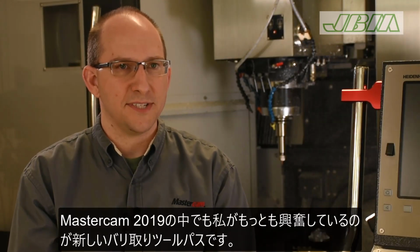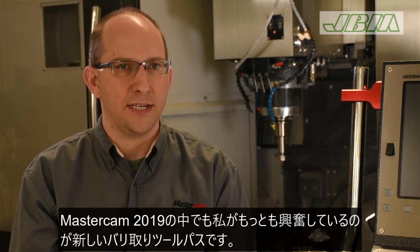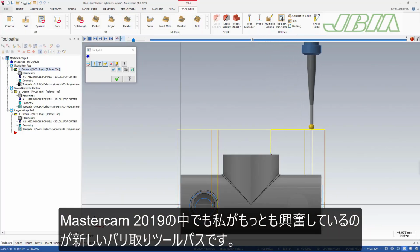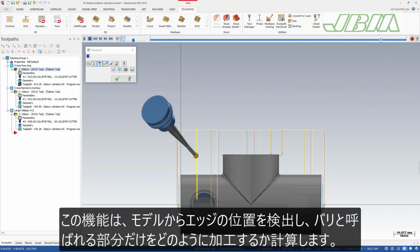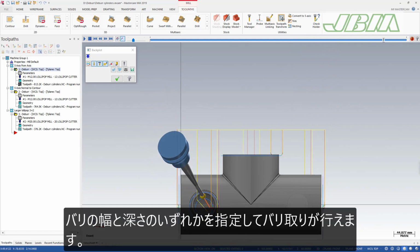One of the features that I'm most excited about in Mastercam 2019 is the new deburr toolpath. What it does is it calculates where the edges of a model are and then figures out how to remove just a little bit at the edge, called the burr. And you could do that either by depth or by width of the burr that you prefer.